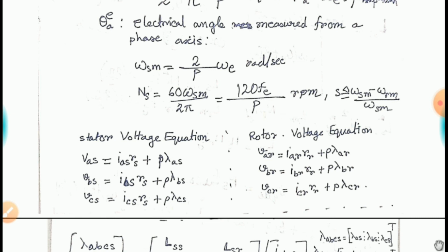On the contrary, the slip ring induction motor's design is not that rugged. It has three slip rings to take the rotor winding terminals out for external availability, and in those slip rings electrical sparking takes place.